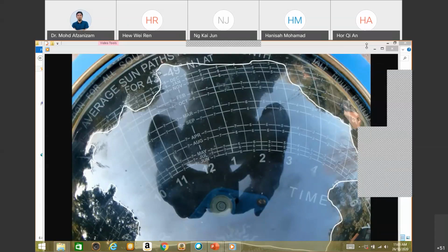you see shading from all of the other large trees going east to west around near the horizon. That's what we want to try to take a measurement of, how much impact that's going to have on solar. The other thing you notice is that the months of the year are shown. In the summer, June, July tend to have about the same amount of time sun in the sky, so they're kind of lumped together. Same with April, August, they're paired up. March, September. The sun is lower in the sky, you see that's near the horizon. So December, November.